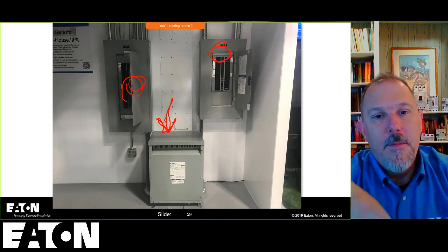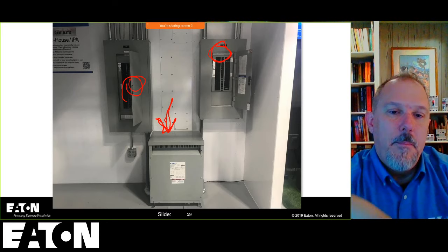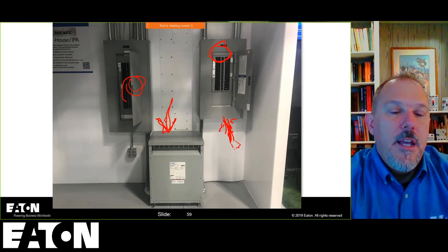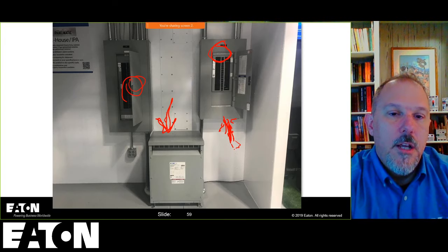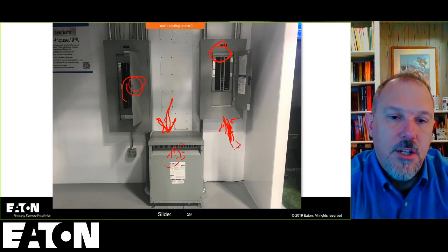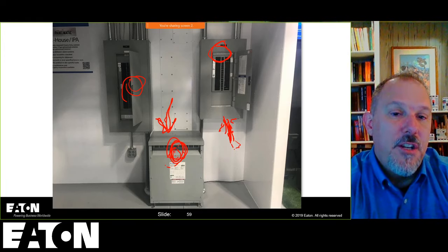the power is not as much of the benefit as if you have to do justified energized work in that panel board. Because if you're doing justified energized work in that panel board, putting the breaker on the secondary in this location here will give you a lower incident energy value on that panel.